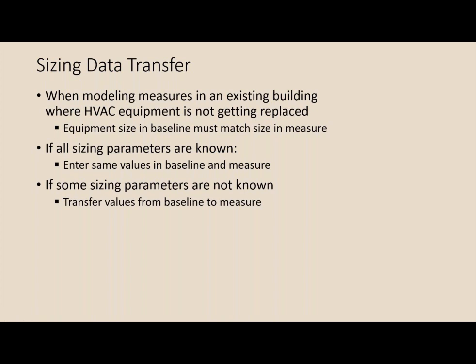So maybe you don't know all of the sizes of the existing HVAC equipment, so maybe you're going to autosize some or all of that. In that case, you would want to do the sizing in the base case model and then be able to transfer key values from the base case model that was autosized into the measure model.